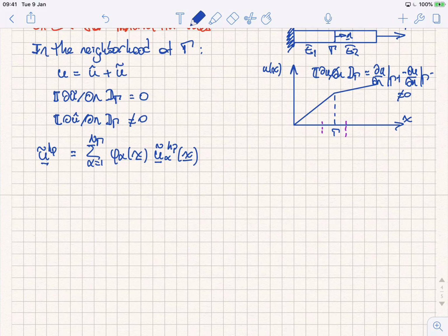But I can still multiply the shape function of node 2 with another function that represents some local behavior. Maybe the discontinuity now is passing through that cloud, right? And then I keep doing this, and I'm using the partition of unity to paste together local approximations in clouds. So that is basically a different way of thinking in terms of our approximation. Okay? Everybody with me there, right?